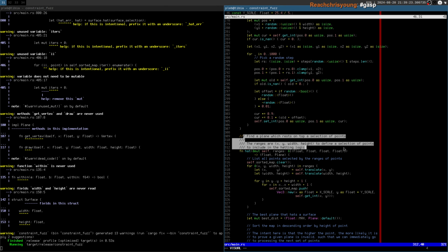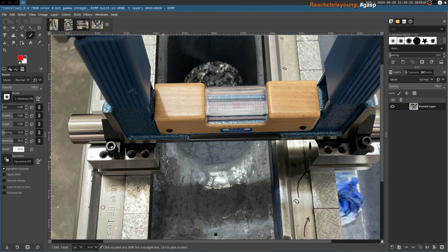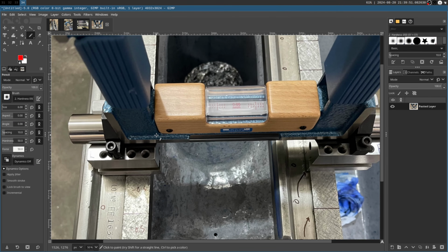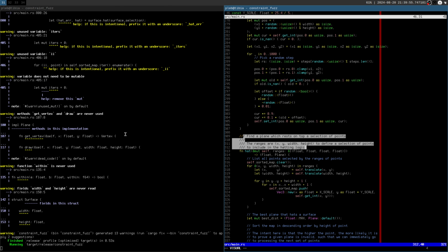That is what I am basically saying is happening in real life: I am setting a perfectly flat plane, flat with respect to my surface plate, which is a very flat reference. Once again, we're assuming that that's perfectly flat. We take that and set it down, and that determines the contact patch across those 2 ways, and thus the reading that will go into the level, right? So I am trying to find where those 3 points would lie for that surface to sit.